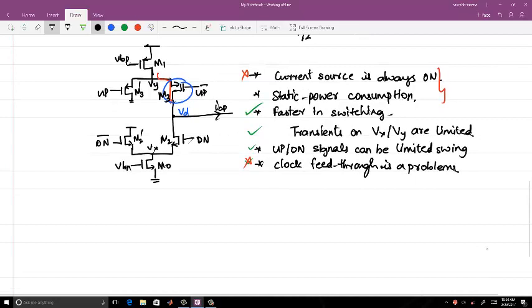Okay, and why do we not want to see them? Because those transients will affect the delta I current which goes into the loop filter. So an easy fix for that is that I connect these two. So sorry, let me just connect it. I remove this, not this VDD and ground connection, but I just make this connection.